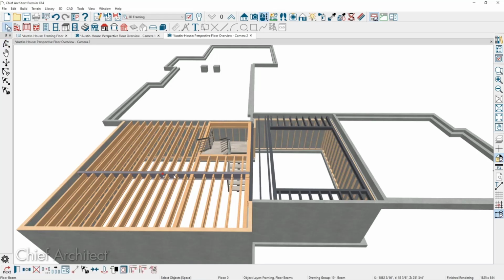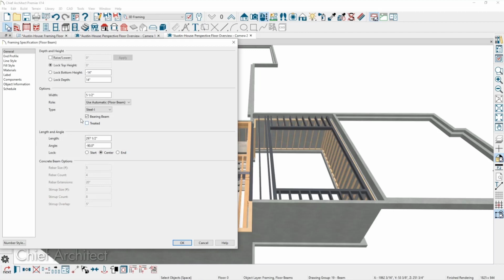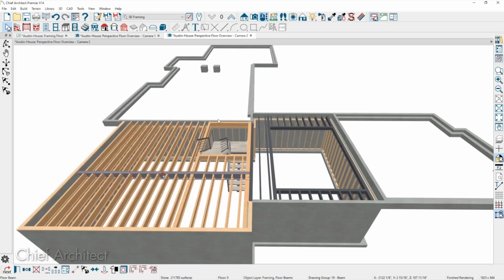If you mark this as a bearing beam, one of the options is you mark it as a bearing beam. Then there are some options. The program is going to look at the span of the pier objects, and if it didn't place them for you, just grab the copy tool and use the multiple replicate so that they're on center based on what you think those should be. All right. And then is there an option for putting bells on the bottom of those piers?